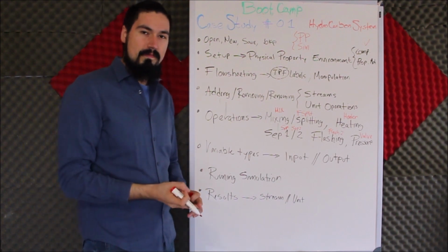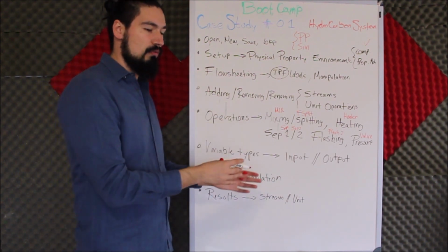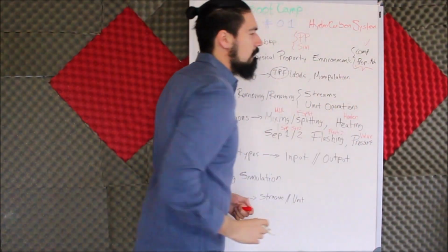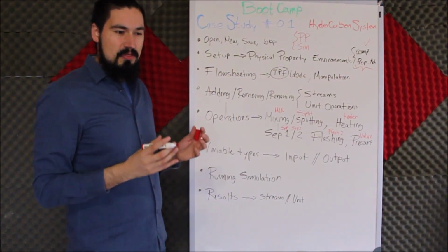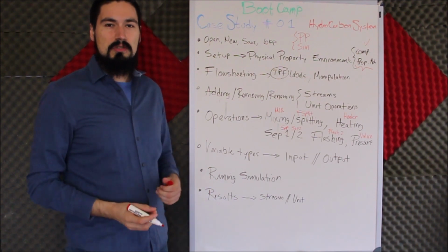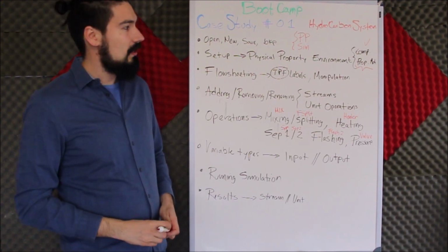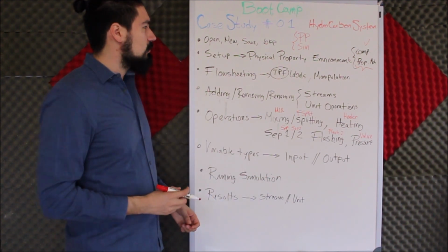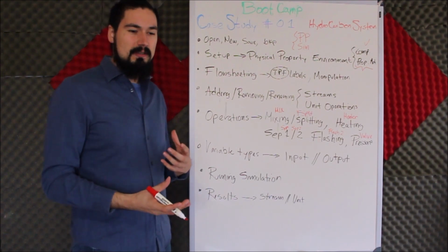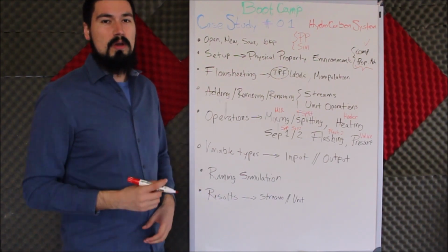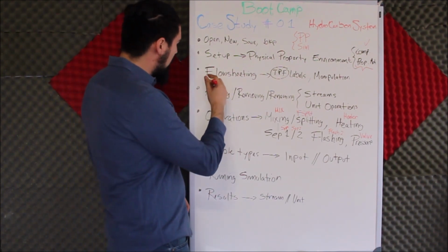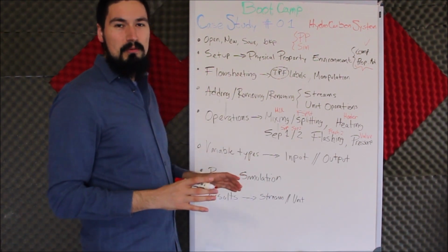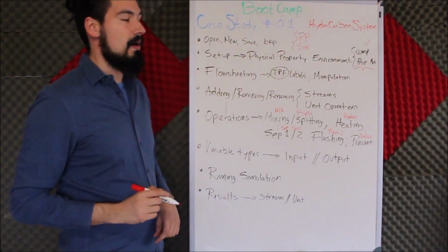to be using, how to find them, how to search for them, how to remove or add existing materials, and the property method, which is essentially the thermodynamic package that we're going to be using, how the properties are going to be calculated, the mixing rules, also what are the activity considerations or the equation of states. Now, once we set up the physical property environment, from now on you will be able to go directly to the simulation environment.